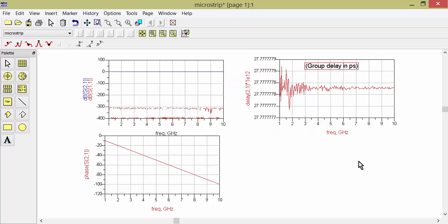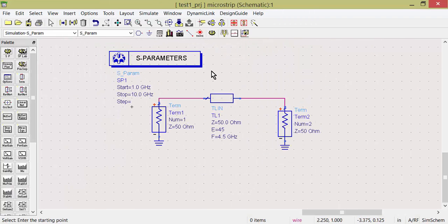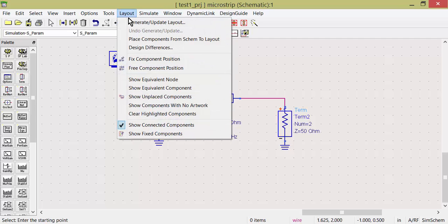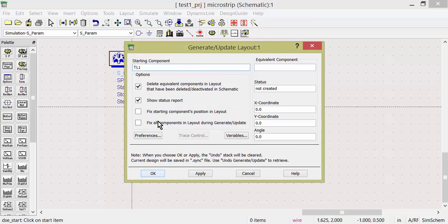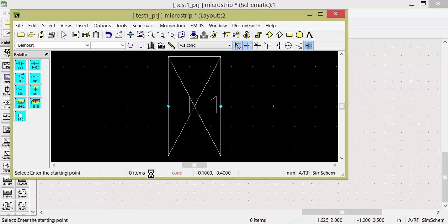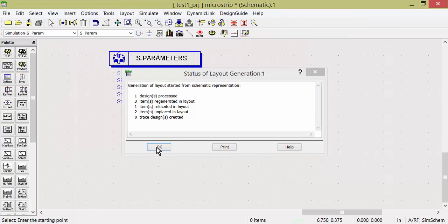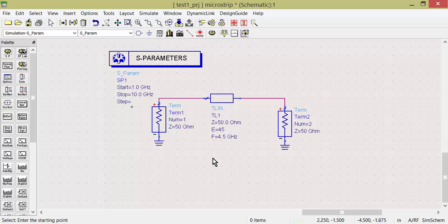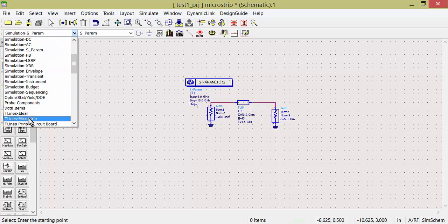Now I have to do one thing. This is the actual circuit model. Then I have to give the transmission line model in microstrip form. Actually, in fabrication and full wave simulation I have to choose a substrate. So first I select a substrate, one transmission line in the microstrip substrate domain. Then I have to select the microstrip substrate. Let's give some properties on the microstrip substrate.